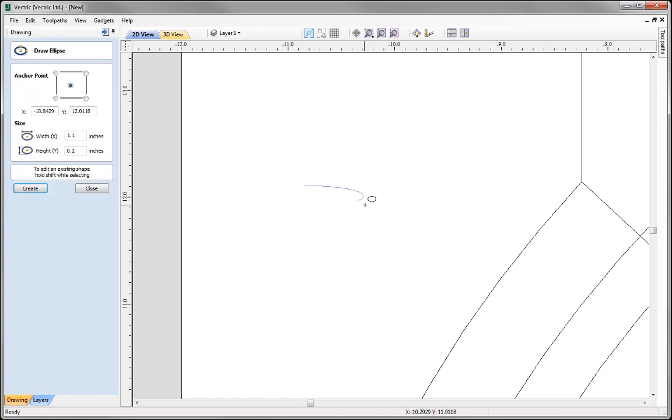So I'm going to pull a shape out that has a width of 1.5 inches. I can see that displayed there. And I want to give that a height of 0.6. So with that drawn out with a 1.5 inch width, I'm just going to type in 0.6, you'll see it displayed at the bottom, followed by Y, and that's going to input that height of 0.6 with my width that we already dragged out of 1.5, and we can see that displayed there.